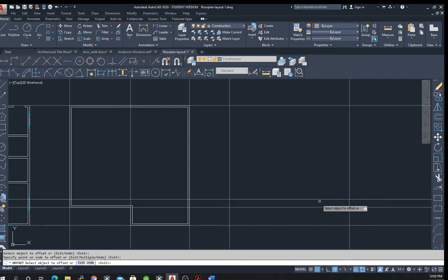and actually I put in 2 feet here. I should have put in 1 foot. We're using let's say 2 by 10s, and then we're adding enough height to give us 1 foot, not 2 feet. So this needs to actually move down by 1 foot.